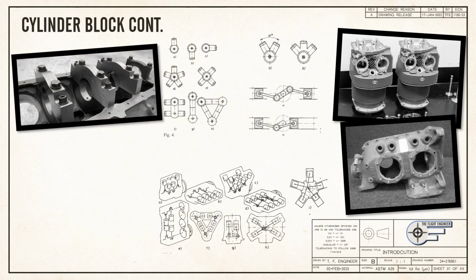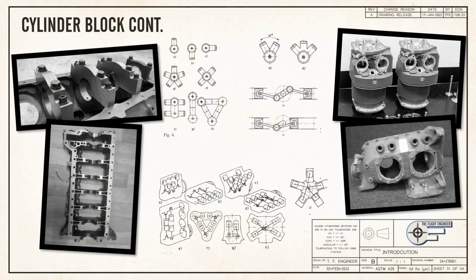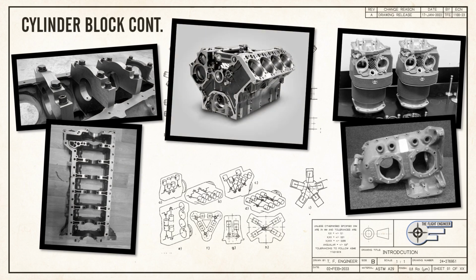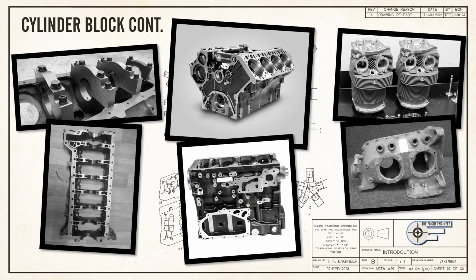They can have separate main bearing caps, or they can integrate them in a ladder or bed plate style. They can house internal pumps for oil or coolant, or function as an accessory mounting plate for these and other external assemblies. It is all up to the engine designer and the demands of the application.